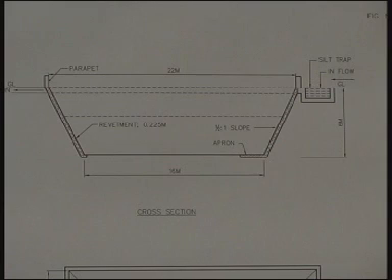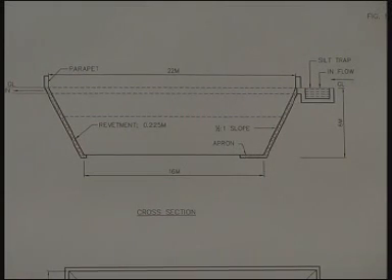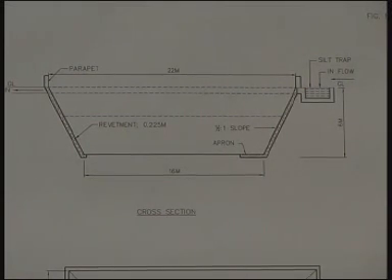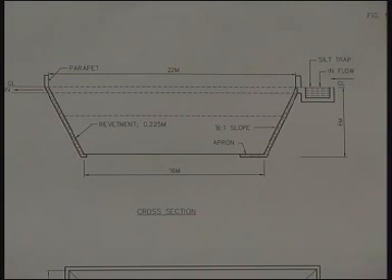So there are three stages. One is the recharge structure within the premises. The second thing is a recharge structure of a much bigger size, 22 meter by 22 meter, for recharging water coming from an area of 10 hectares, which includes the roads and all the open grounds, and ultimately a minor irrigation tank storage structure similar to that across a stream.